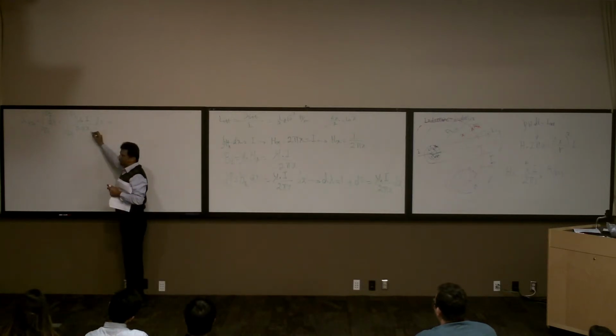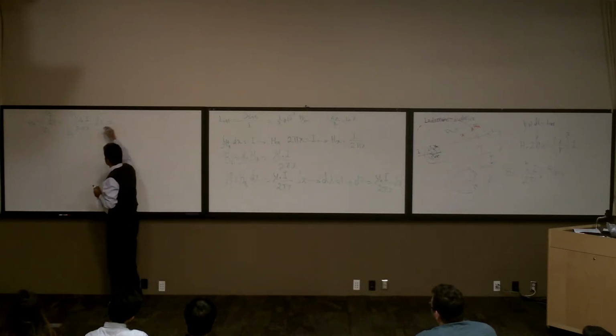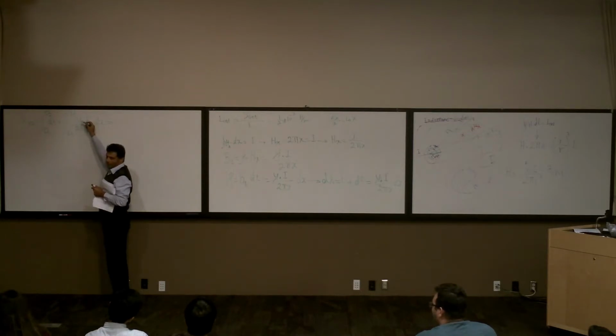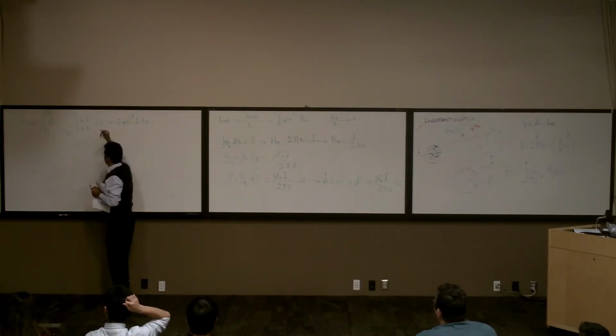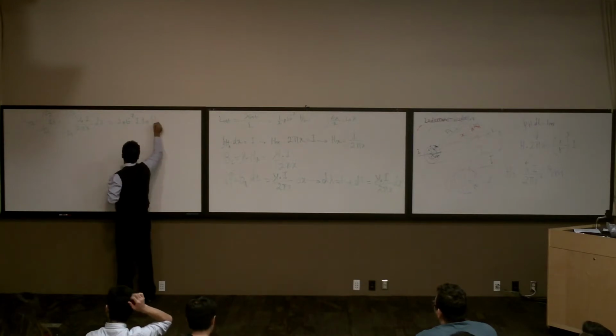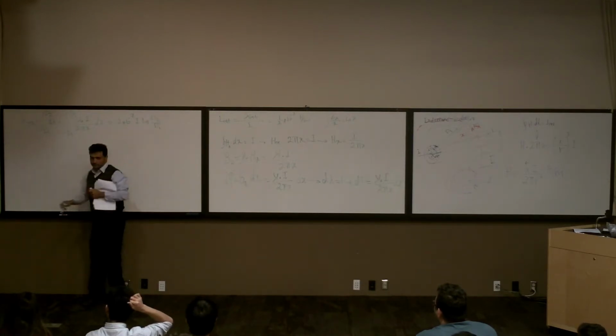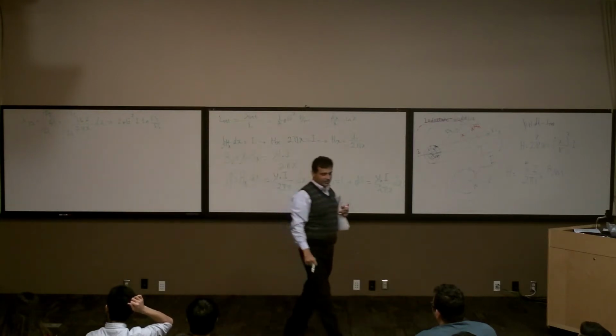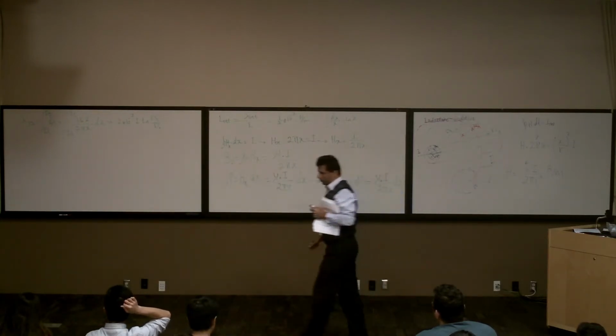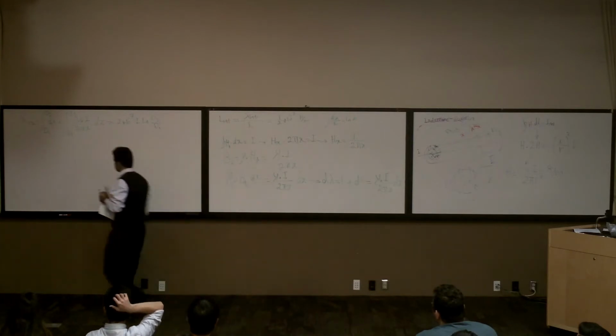So this one is going to be ln of x, right? Basically, mu 0 is 4 pi times 10 to the power of minus 7. It's going to be 2 times 10 to the power of minus 7 I ln of D2 over D1. This is the lambda. Now, how much is L12 if I want to calculate L12?